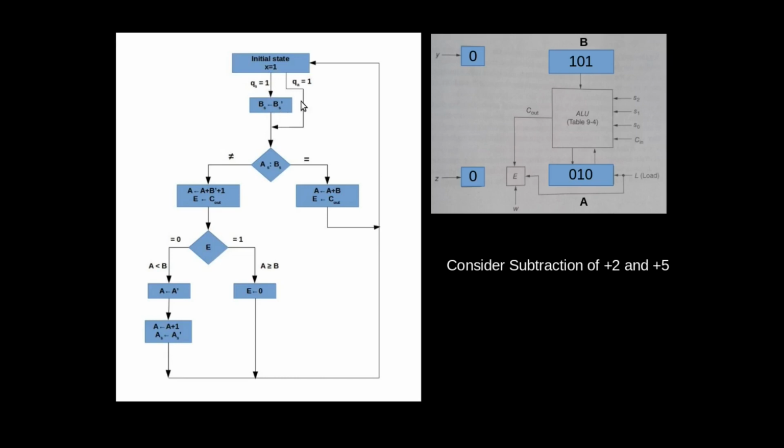Then we have to reduce this subtract operation into an addition operation, or convert that into an addition operation. That we will do by simply changing the sign of the second operand, that is BS is equal to BS complement. This is our B register, this is the BS. So simply complement that one by giving Y control signal as a 1. So this will become complemented. Now this will become minus 5 in sign magnitude form.